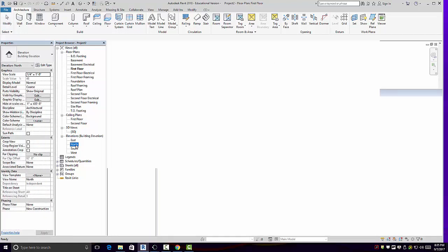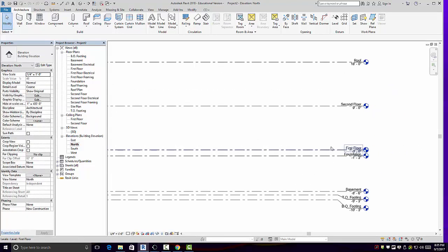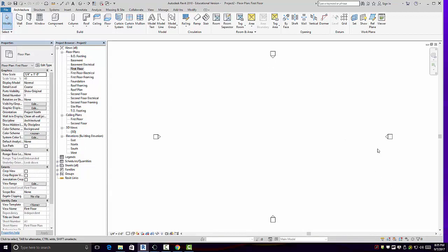If you look at the elevation here, you see these lines. These are actually work planes. It's basically part of a grid system. So these are the floor levels. This is the basement. We've kind of worked with that, and on Tuesday we're going to adjust these. I don't know what they're going to be adjusted to quite yet, but they're set for this. Typically you might have a project where this default may not work for you. So I'm going to go to the first floor to start out. I'm not going to start at the basement, though this does have a basement.